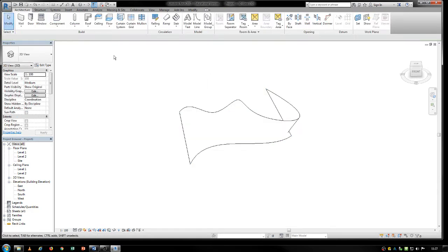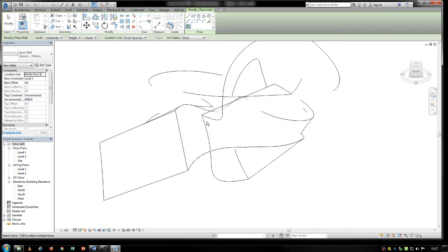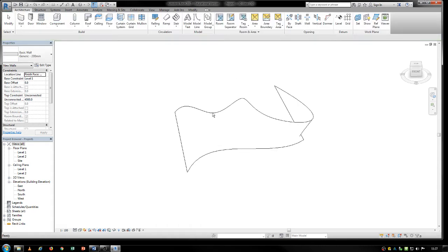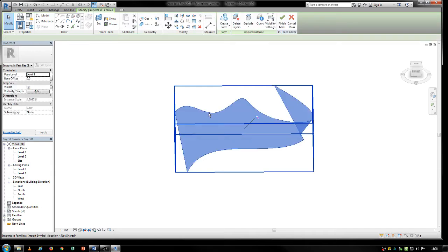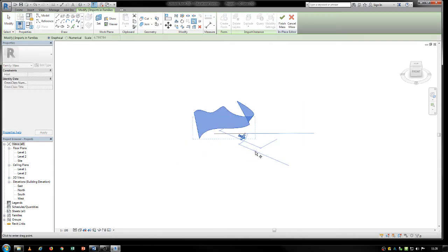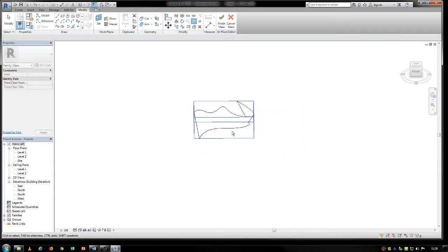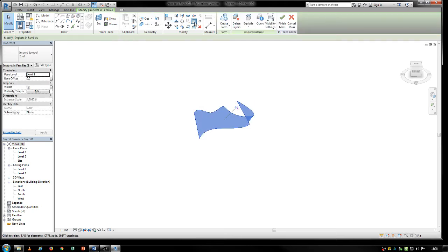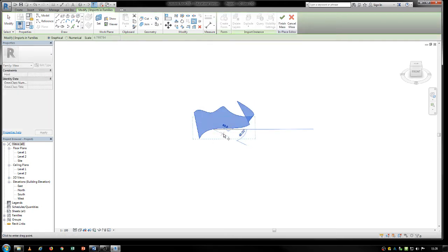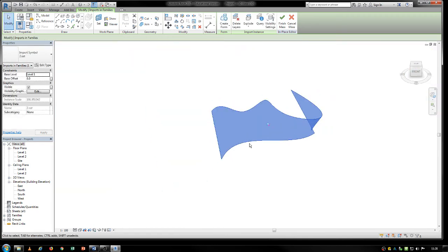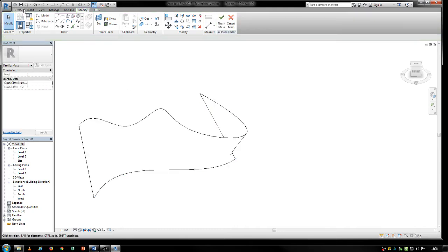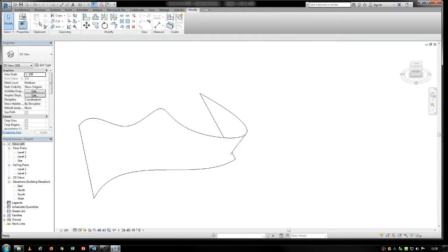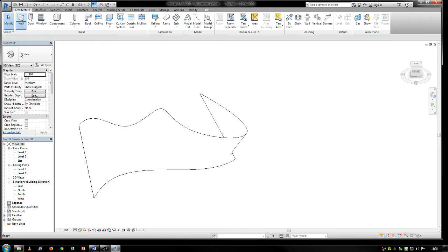The reason this is useful is that you can still go and make a wall by face for this element, and it would give you a wall. It's off scale, so let me just change the scale on this guy. I'll select scale, go from 1 to 40. Hopefully that's right. Check. Go back to wall by face.